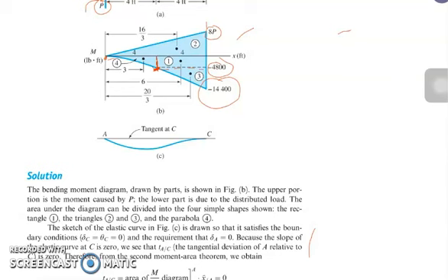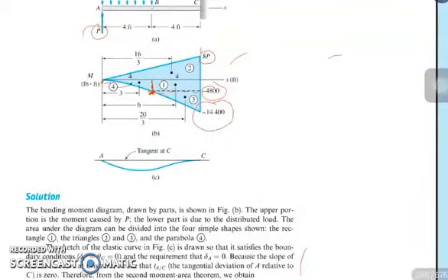For a rectangle, from that point towards this point, that is 1/3, 2/3, so 2/3 of the length. If that is a parabola, from this portion towards that portion, that is 3/4 of the length. So we have now identified 16/3. We have this one as 3 because that is 3/4 of 4. So cancel out 4. So you got 3 for this one.